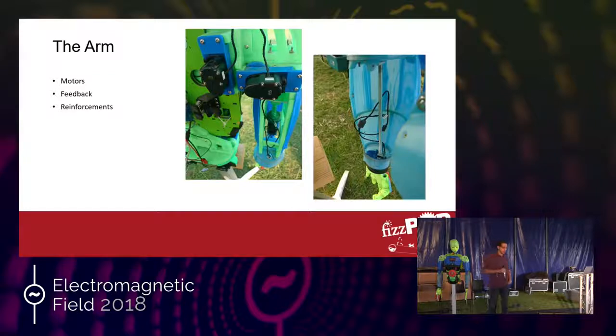Another thing I modified in the arms is that I added some metal reinforcements. So you'll see a rod going down the forearm. Now the forearm is originally printed in about 12 parts that are glued together, and it's rather thin. So if you're trying to lift something heavy, it could break.